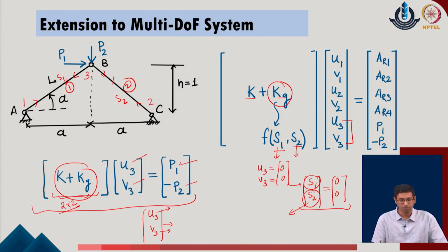We also obtain the values of P1 and P2 as per the initially defined values. But we also realize that once we substitute the updated member force in this K plus Kg term, the value of the forces comes out different than the loads which have been applied on the given system. This is the same problem which we faced earlier in the Newton-Raphson scheme also, and that is where we now start with the modification, going with the iterations in each of the increments of the given system.